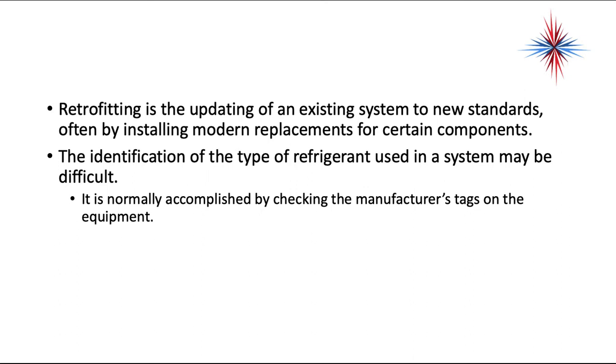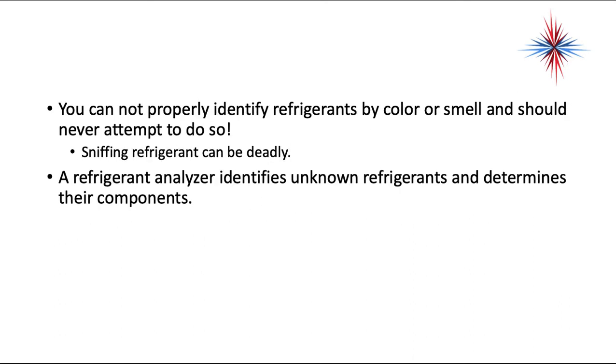The identification of the type of refrigerant used in the system may be difficult. It's normally accomplished by checking the manufacturer tags on the equipment. However, in the lack of manufacturer tags, you cannot identify refrigerants by color or smell and should not attempt to do so. Sniffing refrigerant can be deadly.